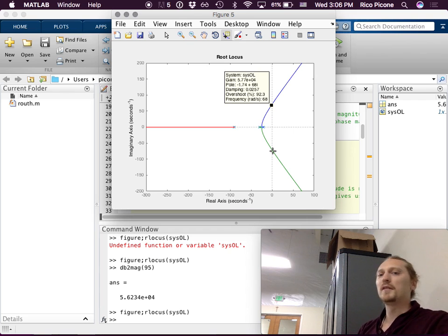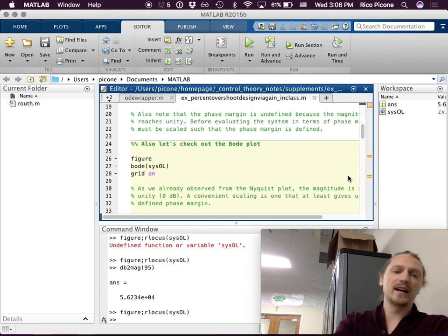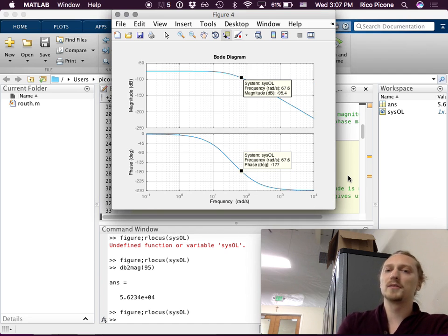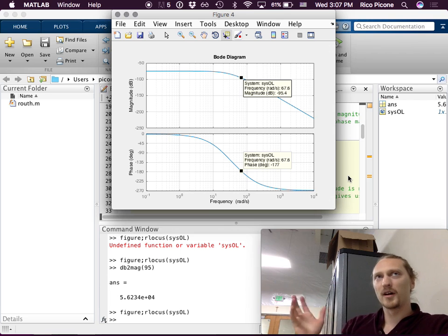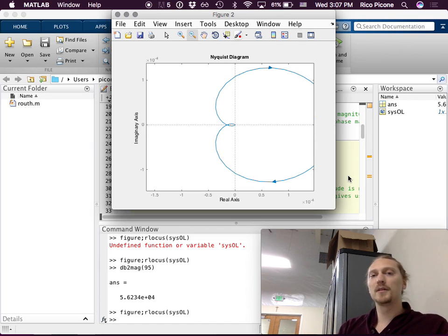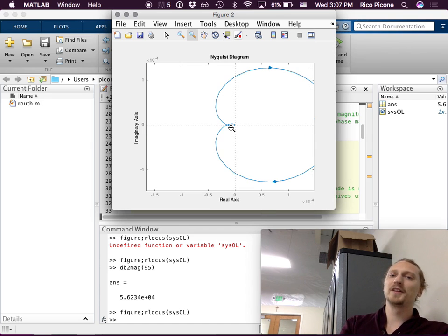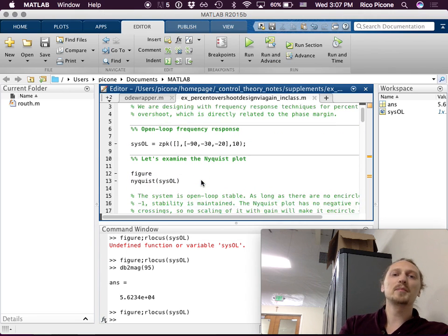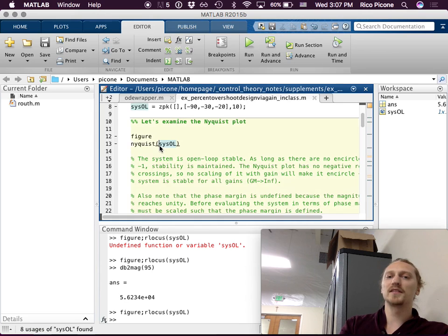So we know how to do this with root locus, finding the gain at which it becomes unstable. But now we can see how to do that with a Bode plot as well, looking in terms of phase margins and gain margins. Yeah. You could also do it with a Nyquist diagram, right? Because we could bump the gain up on this. We're just playing at this point, but I think that it's good to do.